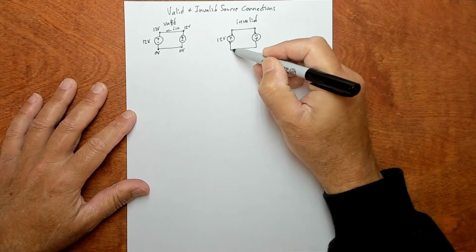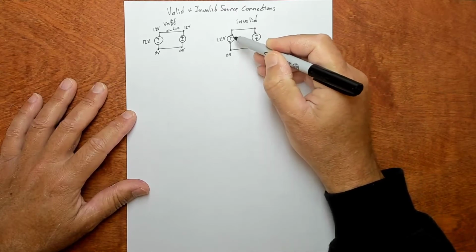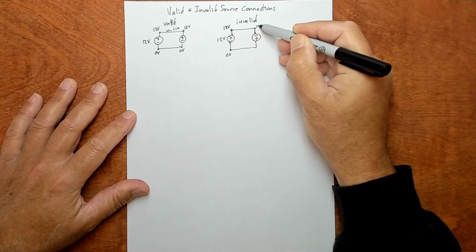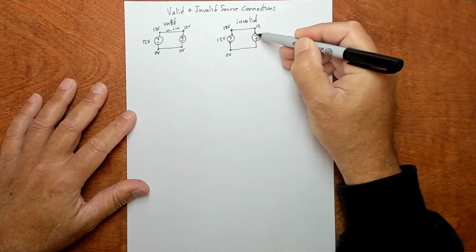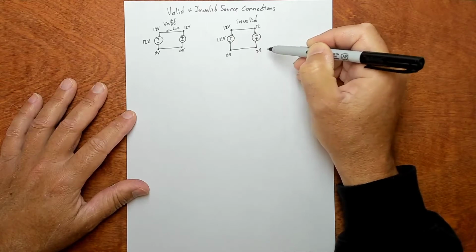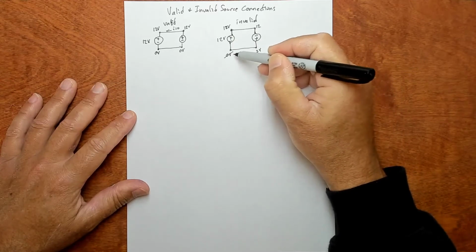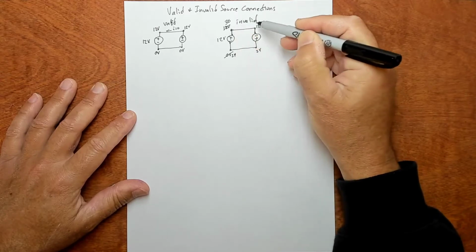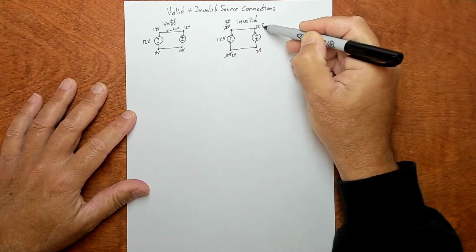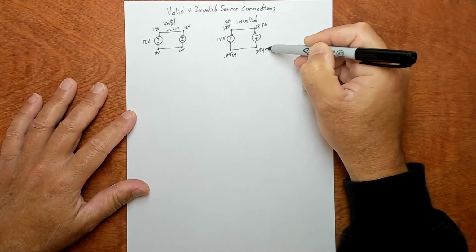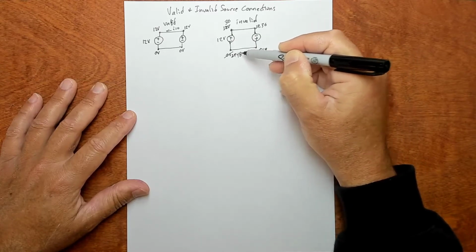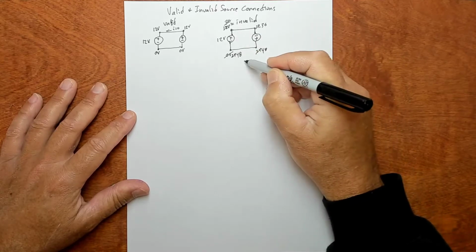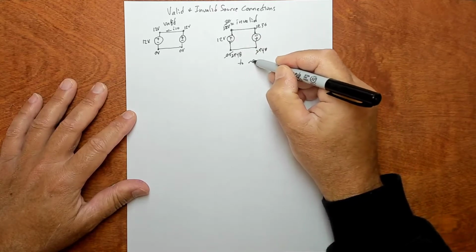So what's wrong with this? Let's start here and go with 0 volts. So we're going to come out of this thing. We're going to have 12 volts. Let's bring the 12 volts across here. All right. And then we're going to go through this guy. We're going to come out here. We're going to have 24 volts. So, that makes this 24 volts, which means we're rising up 36 volts, which means bring the 36 over here, which means we're rising up 48 volts, which is bring this 48 over, so 72, and it's to infinity.